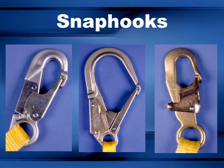Snap hooks are a crucial component in many rigging and safety systems. They're designed to connect and secure equipment quickly and reliably. One of the key points to remember is that snap hooks should always be inspected for wear, deformation, or damage before use to ensure they function properly. Their ease of engagement and release makes them very practical, especially in situations where quick connections are necessary.